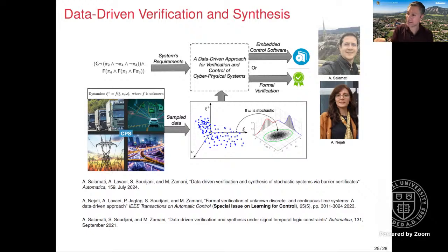But if I have one trajectory from the system and assume it's lengthy enough, I also need to assume it's persistently exciting enough, right? These are the assumptions for identification. So under some appropriate assumptions, even if the dynamic is polynomial type, I can identify a model of the system, and I use that identified model to do everything I did here. I'm sure there are many works being done in the control community, which are called indirect data-driven. They try to identify a model using a single trajectory, and then use that model to design a controller for safety or stability or other property of interest.